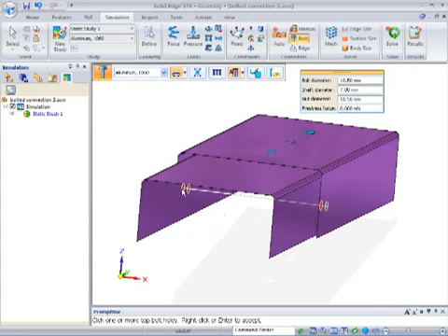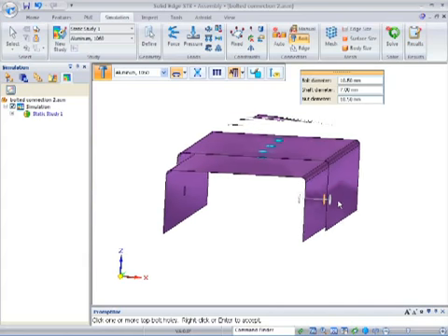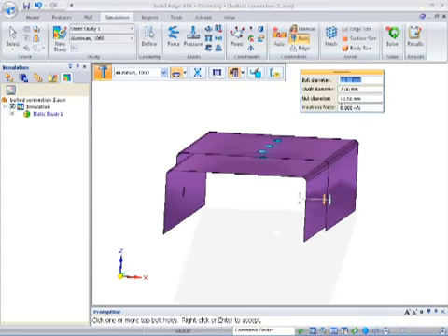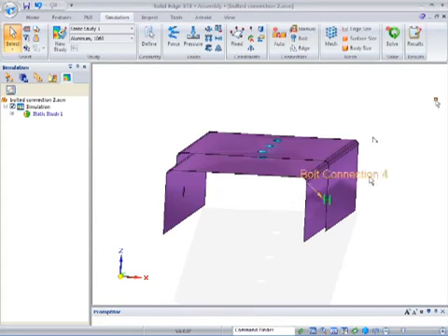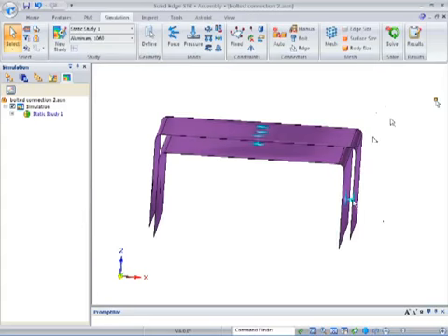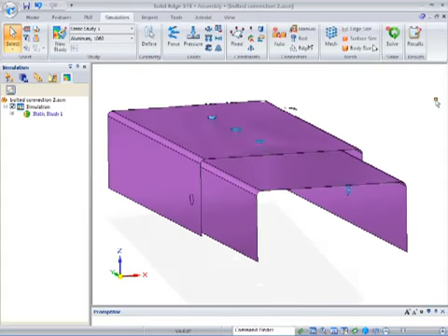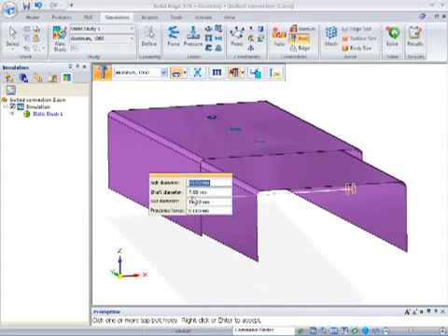So all you have to do is come to the end and grab that sphere and just simply drag it back and change the search value from the top to the bottom here. Key in our pre-stress value again of 100 millinewtons, right mouse button click, and it creates that bolted connection for the right side. The only thing that's left to do is create the bolted connection on the opposite side.